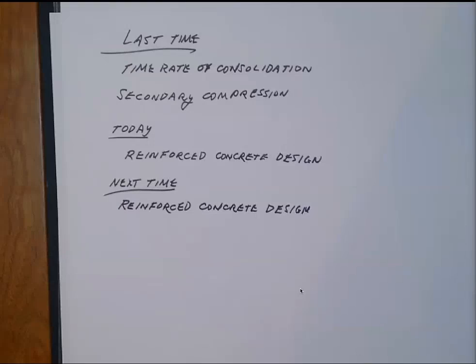of V, the coefficient of consolidation. And that analysis involves some graphical construction, identifying points on the curve, and determining from that a small t50, a small t90, which are real times, typically in minutes for laboratory data. And you use that conventional equation with H drainage squared, big T, little t, and so on included in that, which we'll be doing quite a bit of in the class.